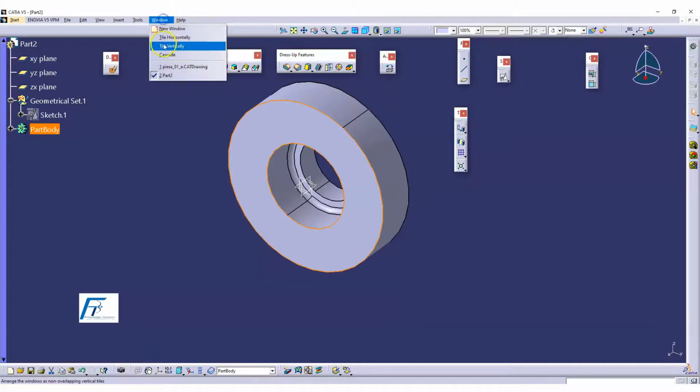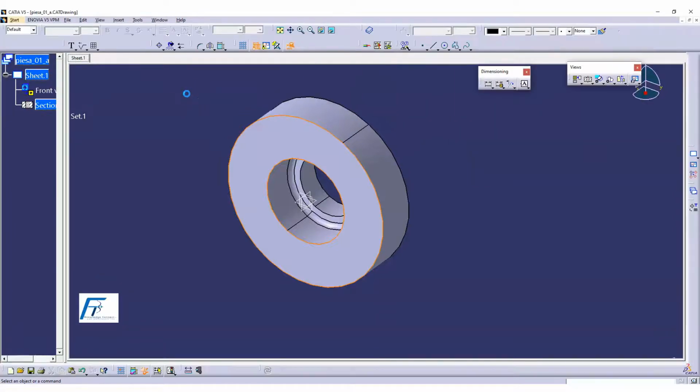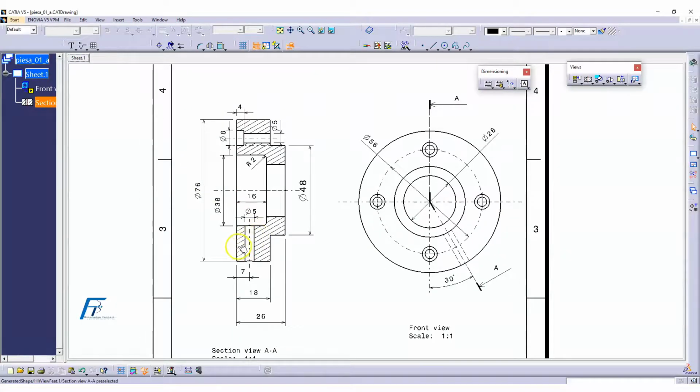Now, this is my drawing. Just let's go and understand the drawing better. From this top face, the hole is at a distance of 7 mm. So I'm going to just create this profile. That means I would like to create the center point of the hole, which is nothing but from here 7 distance from the top face.